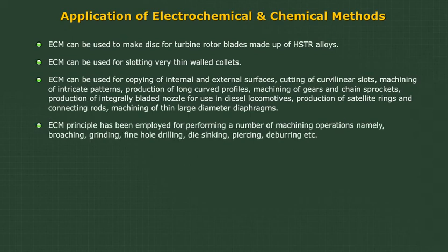ECM principle has to be employed for performing a number of machining operations, namely turning, planing, broaching, grinding, fine hole drilling, die sinking, piercing, deburring, plunge cutting, etc. ECM can also be used to generate internal profile of internal cams.